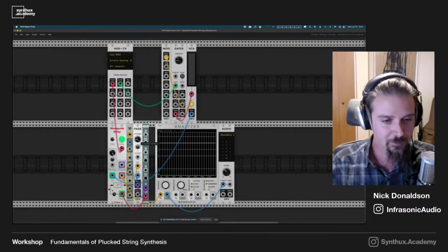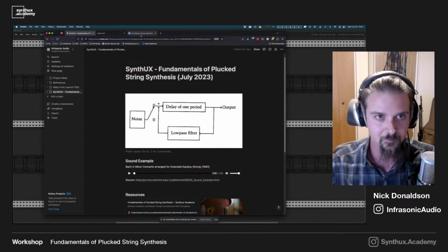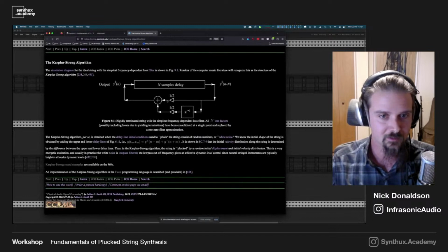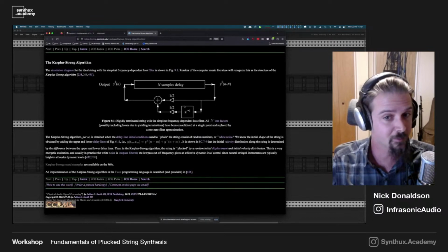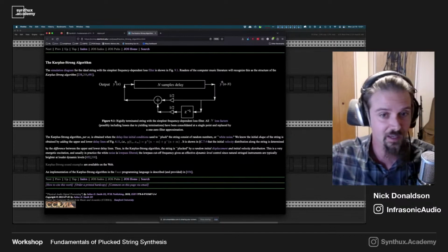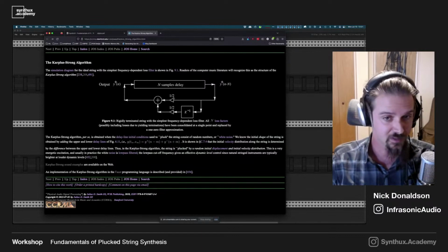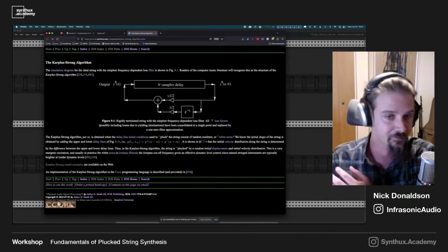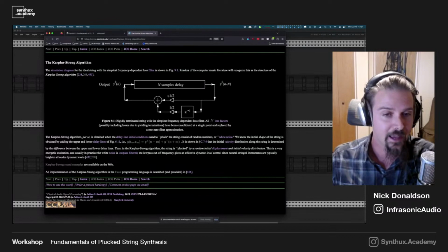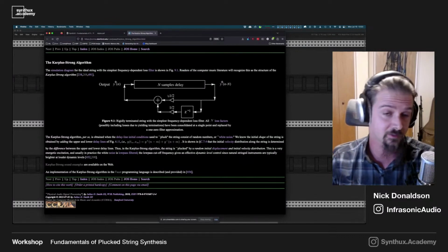So the low pass filter in the original algorithm is extremely simple. It looks like this. It's really just a 2-sample moving average. So it's the current sample plus the z-1, which means the previous sample. So it's saving a sample from the previous iteration, and it's taking the average of those. It's multiplying both of those by 1/2 and summing them. And when you take the average of 2 samples or more, it's a FIR filter. Technically, that's having a low pass effect, a very gentle low pass effect.